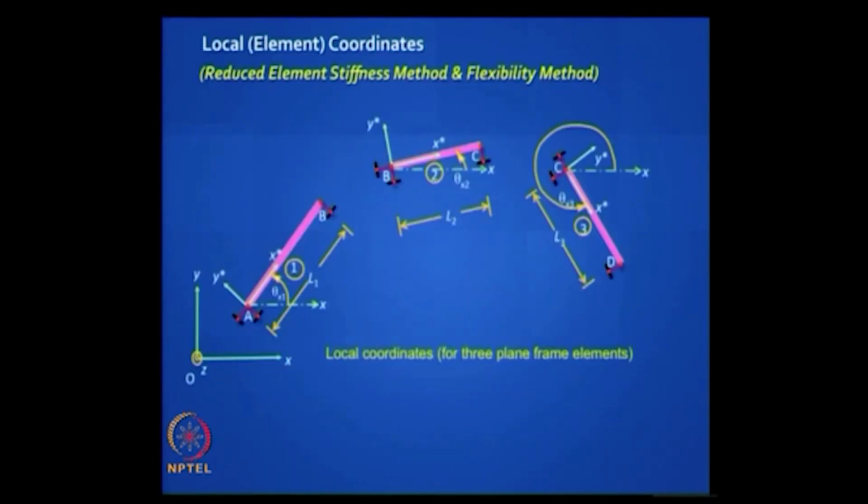So let's look at this problem. We did this earlier, right? Now I have given 3 supports, okay, I can give any 3 independent supports. You see these things? I have actually made it simply supported. These 2 rigid links say that this joint cannot move. This rigid link says it can move horizontally, it is like a roller support, but it can't move vertically. Now this element is stable. If I apply loads on it, it will resist those loads.